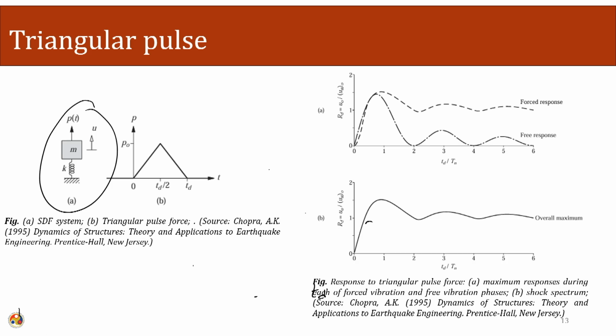Corresponding to our choice of degree of freedom and our choice of mode shape, the shape function will change, and that will have an effect on the equivalent mass, equivalent stiffness and equivalent force. Those effects will be translated over there. So, for any given system we can choose any degree of freedom which we require and any mode shape which is of interest to us. We just need to change the corresponding deflection equation, or choose the point where we are calculating the degree of freedom. The mode shape effect will be shown in the numerator, and the effect of the choice of degree of freedom will be shown in the denominator.